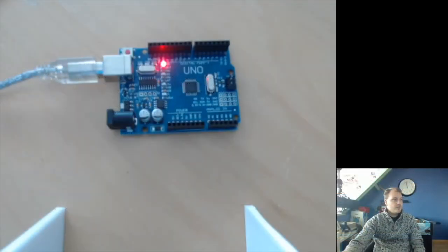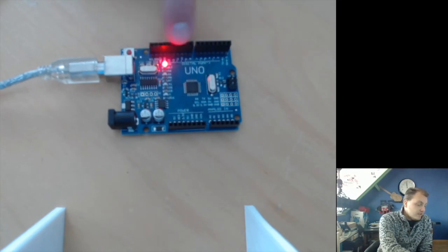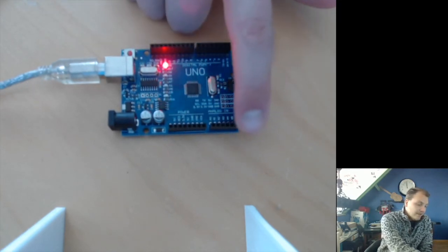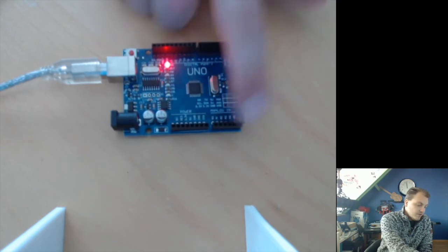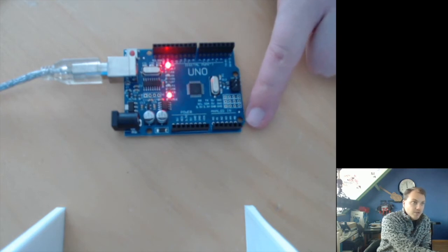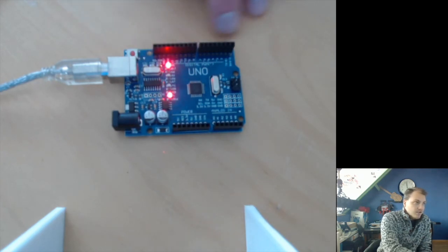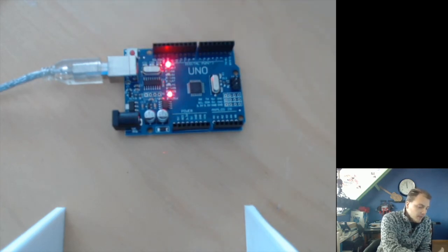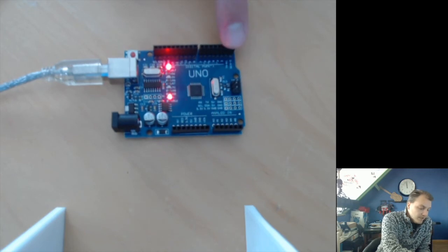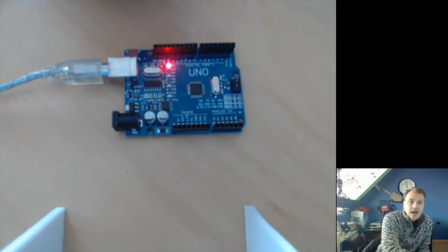Let me switch over to the Arduino cam. You can see here that we have digital inputs and outputs, and we have analog inputs, which are used for measurements. If you want to measure a voltage, for example, then we use these analog measurements. Digital inputs are most of the time high or low, and we can read out this digital input, but we can also send high or low voltages to this digital pin.